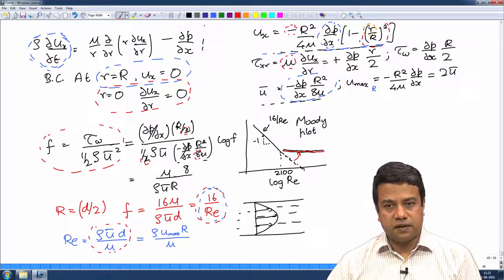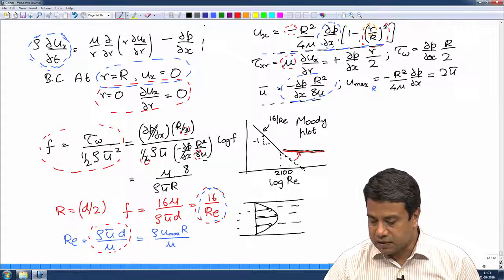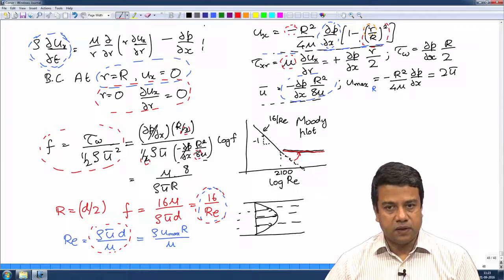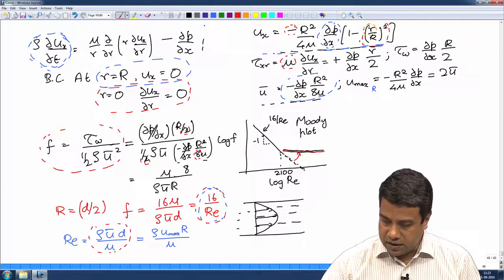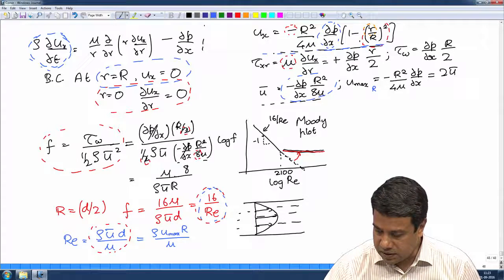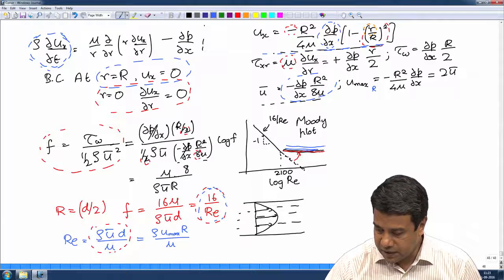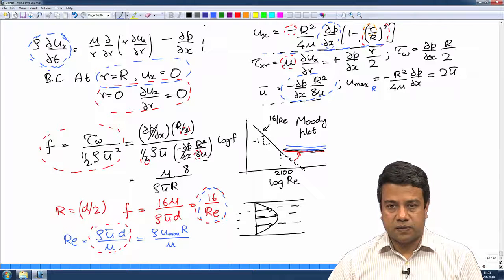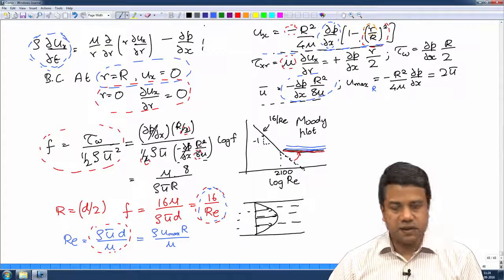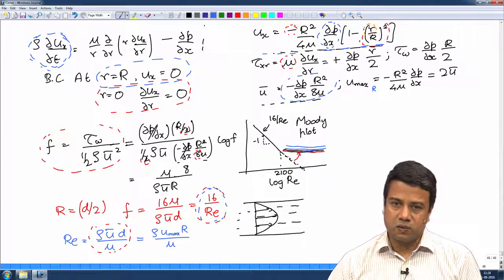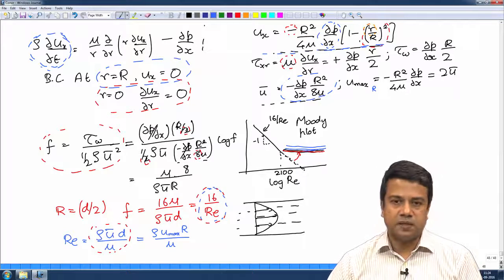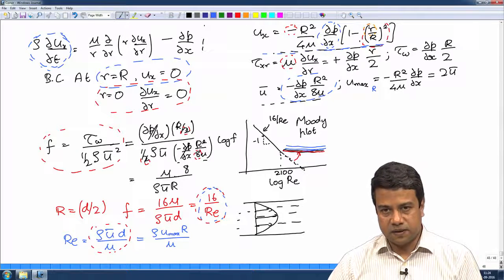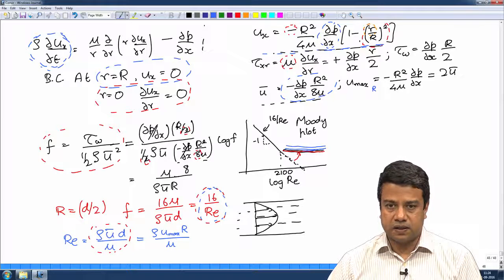And the friction factor in experiments is dependent in general on the roughness at the wall of the pipe. You have a lower value for a smooth wall, and as the wall roughness increases you get a higher and higher value, depending upon the roughness. Those are characteristics of what is called a turbulent flow. So, in this lecture I will try to give you some physical insight into what happens in turbulence. It will not be as quantitative as we were able to do for a laminar flow, because turbulence is a complicated phenomenon, not completely understood yet.